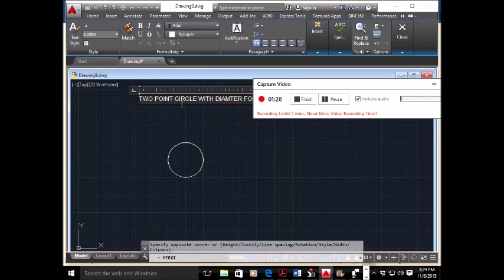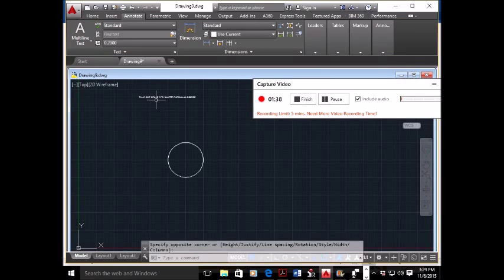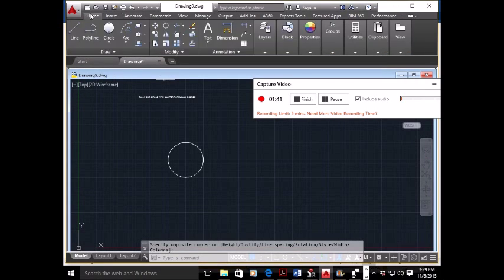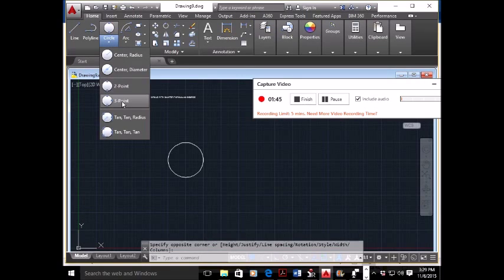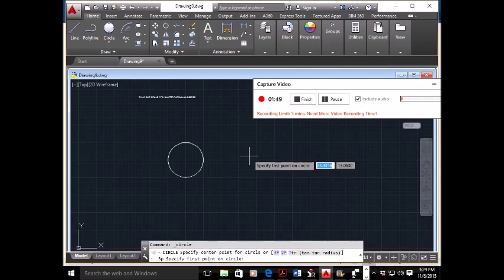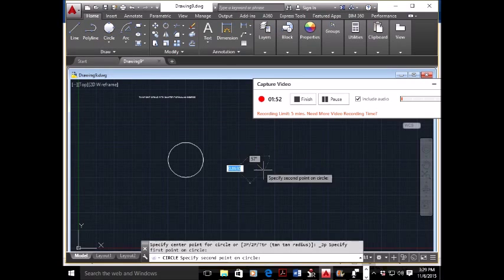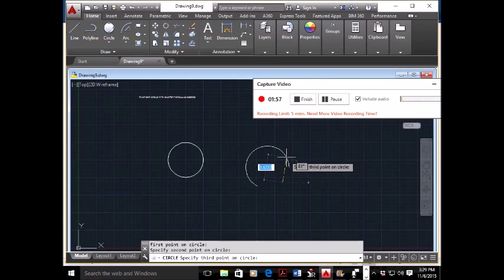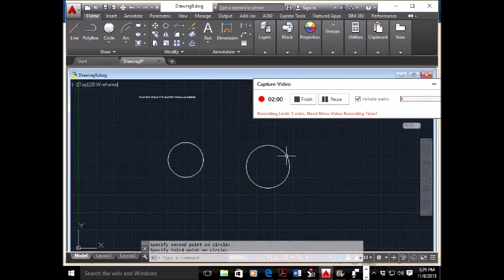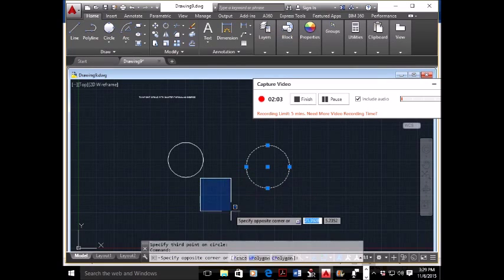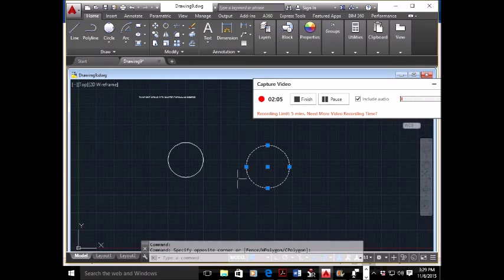You can use single-line text to create one or more lines of text, where each text line is an independent object that you can relocate, reformat, or otherwise modify. Use single-line text to create one or more lines of text, ending each line when you press Enter. When you create single-line text, you assign a text style and set alignment. The text style sets the default characteristics of the text object. The alignment determines what part of the text character aligns with the insertion point.